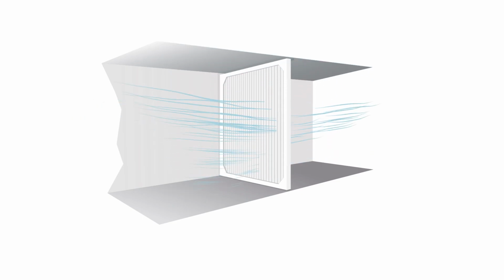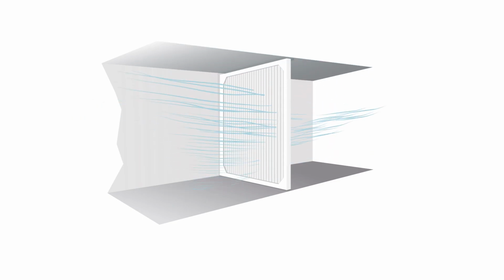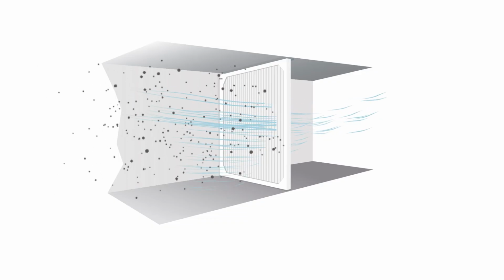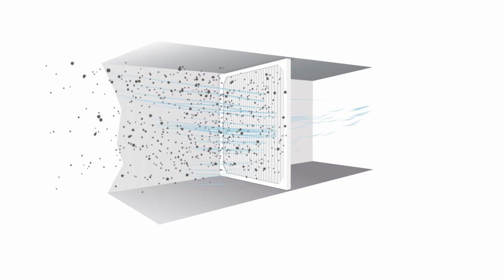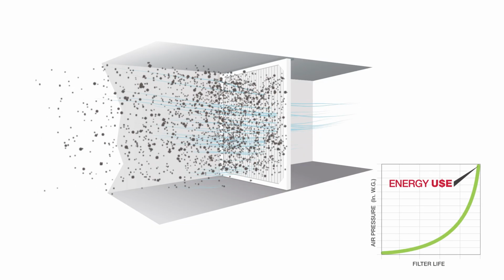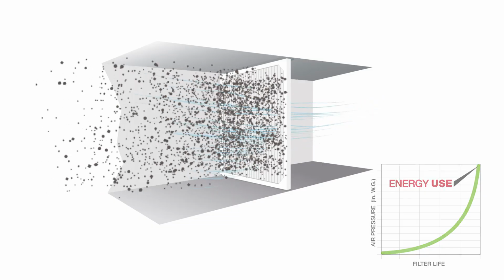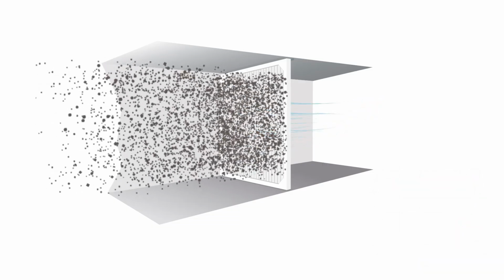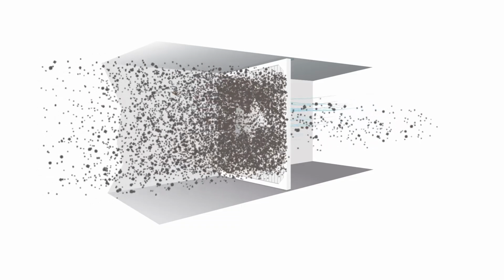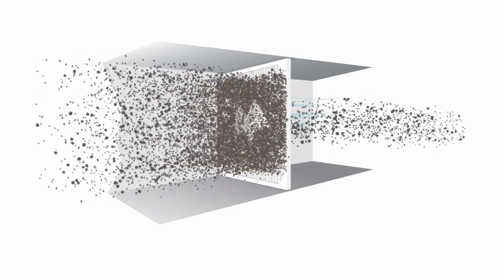If maintenance is delayed in a facility and filters are not changed, the AHU is running very inefficiently, since as the pressure increases, so does the energy required to move the air through the filter. Therefore, the facility will start to see higher energy costs as a result of deferred maintenance. If this continues, the filter will eventually become so overloaded it will blow out or rupture, meaning that it's not providing any filtration at all.